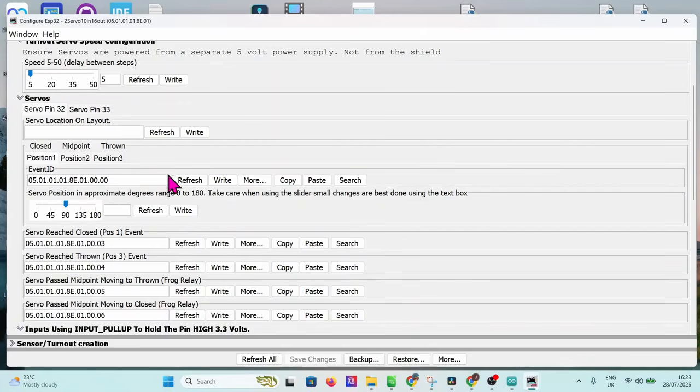And then what you've got here is an event that you can use to teach your JMRI or other nodes. Also inputs from either this node, because it will consume its own events, or from another node. You can actually send this event number and the turnout would be moved for you to its position 1. Obviously when they come, they will come with the value here set to 90 to allow you to set up your servo and your turnout.